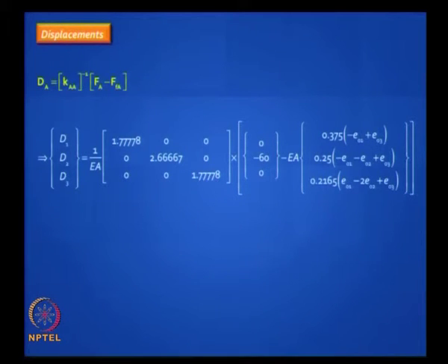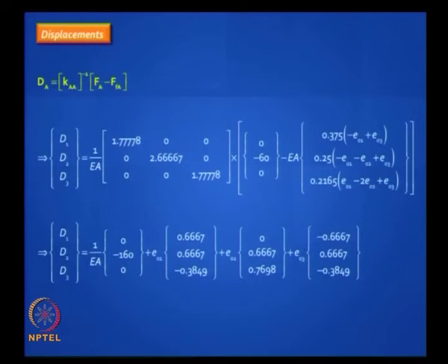You have got your load vector now. So I have inverted my K matrix, it will look like this, very easy to invert because it is a diagonal matrix. This is my load vector FA, and this is my fixed end force vector with a minus sign with all that arbitrary E01, E02, E03. When I actually do this multiplication, I will get some displacements, okay. I will get definitely there will be displacements caused by these lack of fit issues. So I will get dA, I will get d1, d2, d3.